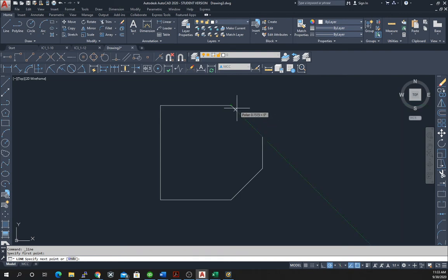So what I'm going to do is I'm going to just type @2 angle sign -45. Now the -45 is exactly the same as the 315, but I wanted to use the -45 because the print shows those angles as 45 for the bottom part, and because it's symmetrical, the top one would be -45, which again is the same as 315. So when I do that, it draws the line in like that. And again, we have the same line and the same angles we had before. All we have to do is shorten it up. Okay, so that takes care of the outside.